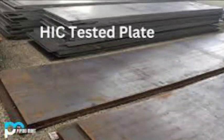When you are having an internal cladding with corrosion resistant alloy like stainless steel or 625 or those sort of thing, then the backing material, that is the backing carbon steel, will have to be NACE compliant, but HIC testing is not required. In some of the specifications, they specify like that. When you use a plain carbon steel or internally coated carbon steel plate or welded pipes, then that time the internal coating is not resistant. So basically, they will call for HIC testing. The HIC testing is waived for carbon steel in case of CRA cladded or like that. That is considered to be a barrier, and it reduces the tendency of HIC to the backing carbon steel.